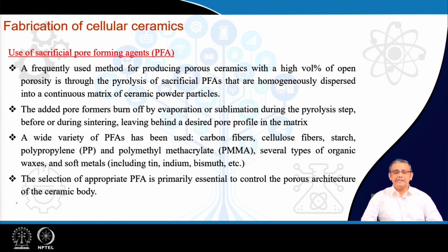If sodium chloride is used as a pore forming agent, then there is one final step after the fabrication of the sintered body, and that is called leaching out. In this case, the sodium chloride remains within the structure, and if the sintered body is put under water for a sufficient amount of time, the water will leach out the sodium chloride, and one obtains a porous body.